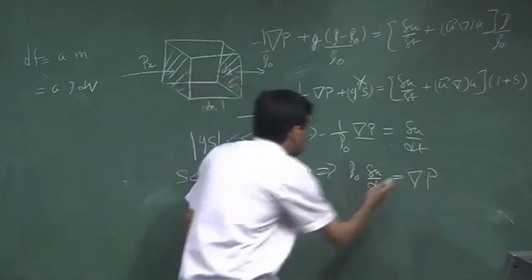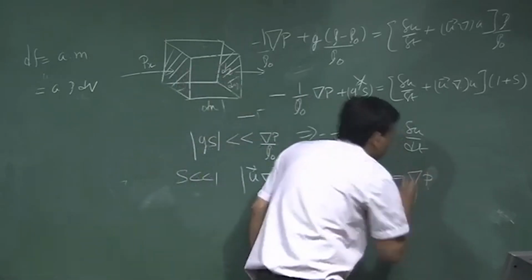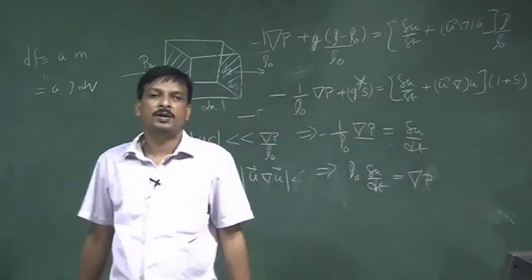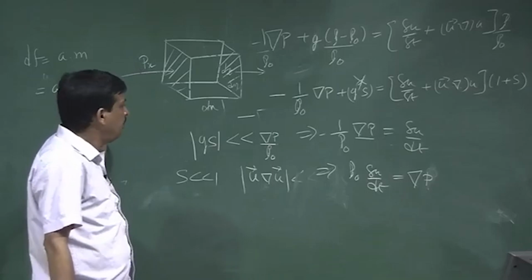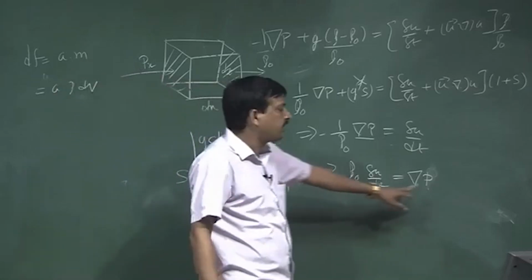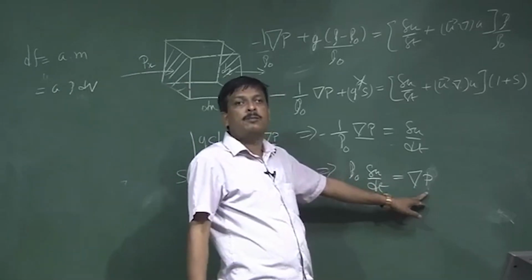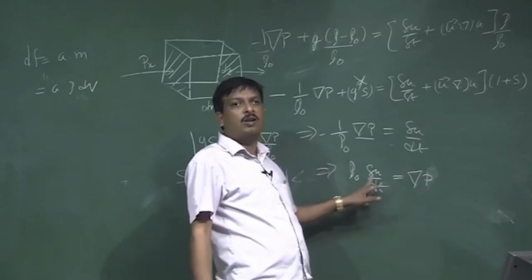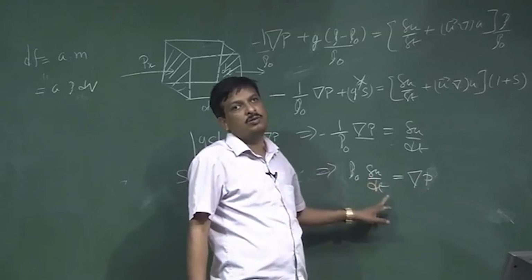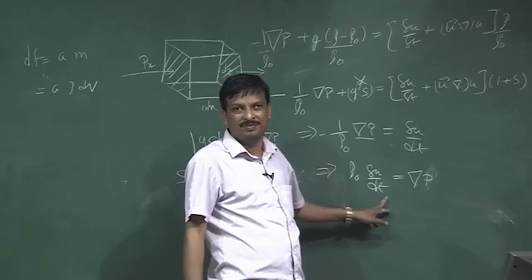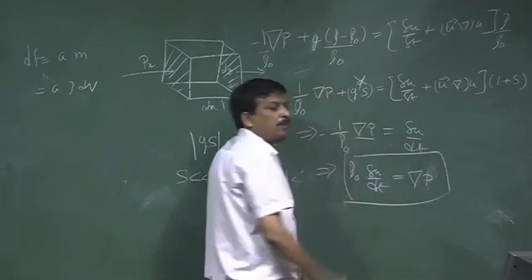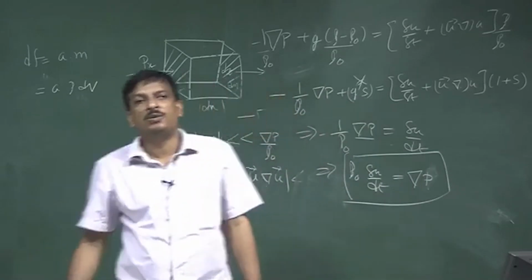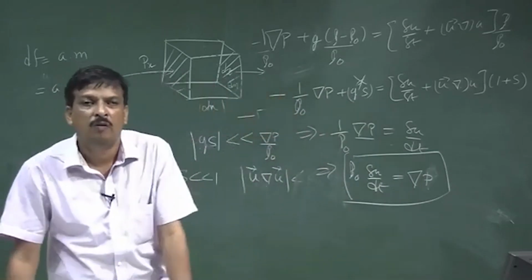So, it is not total pressure, it is acoustic pressure, small p, because we have considered that, which we have derived. So, I get acoustic pressure as a function of acoustic velocity with respect to time. This is called the force equation, sometimes called Euler's equation or the force equation.